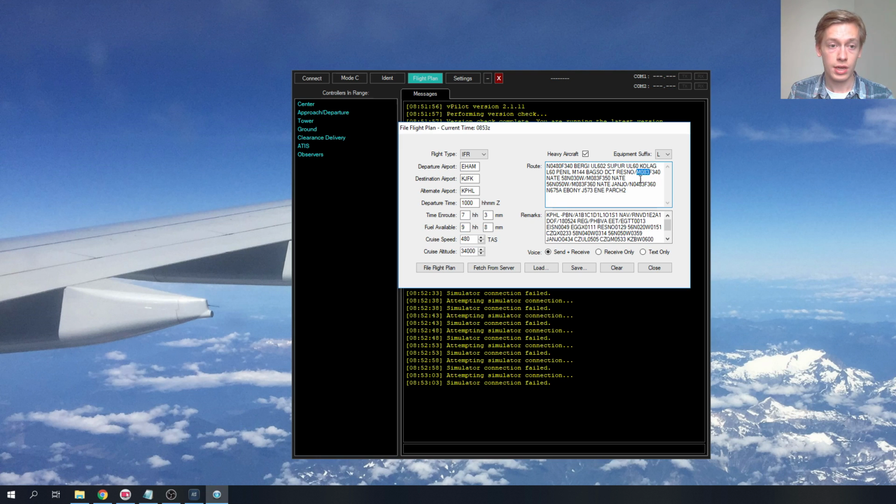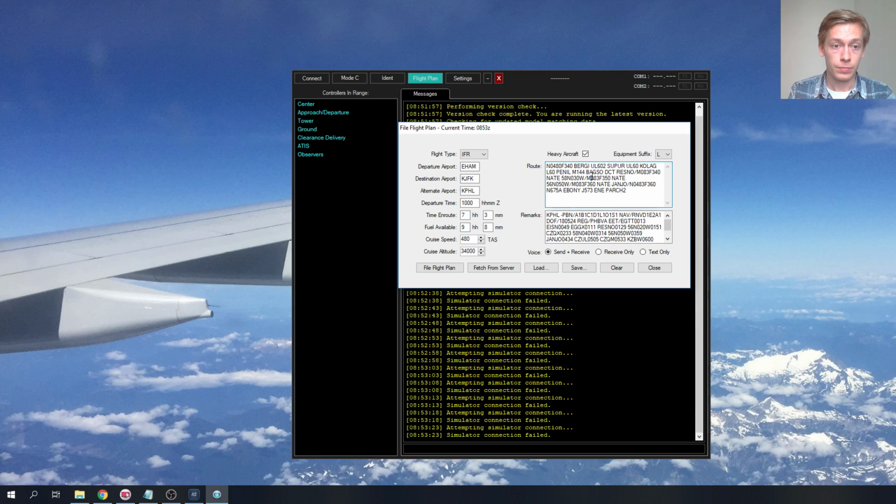So of course, again, once we go to the oceanic clearance procedure, you will notice that you have to report and request a Mach number for your flight. So we're going to expect that we are going to request Mach decimal 83 for crossing the oceanic region on NAT track Echo at flight level 340. Now, as you can see, it does include a step climb. I'm just going to remove that because it's not necessary, because we'll likely not be able to do a step climb anyway. So I'm just going to remove all this right here and do it this way.